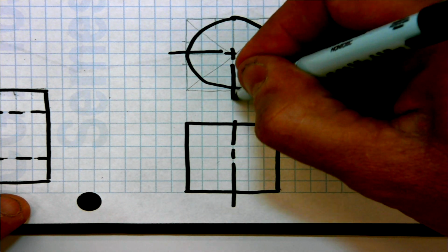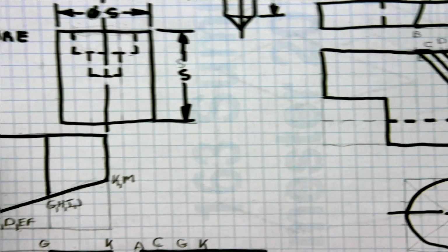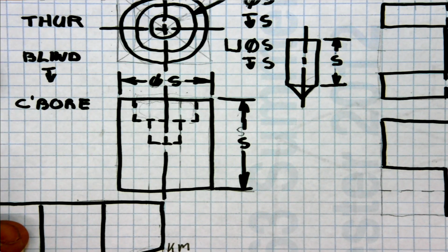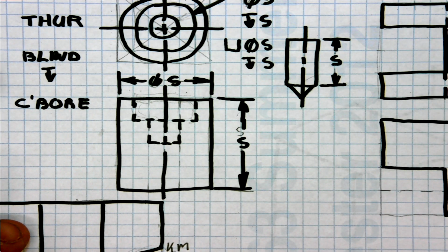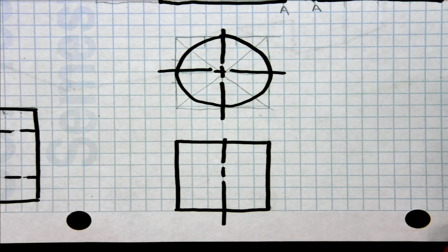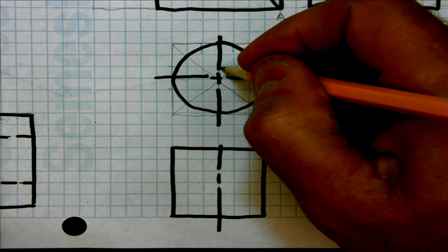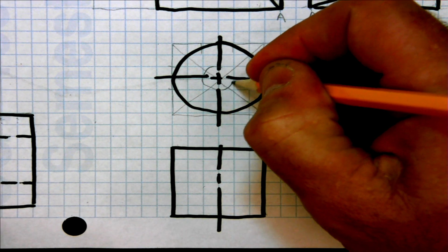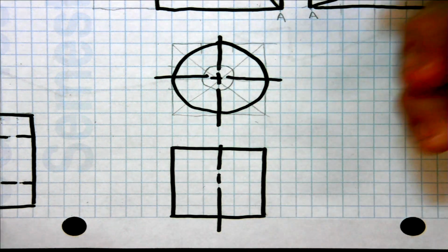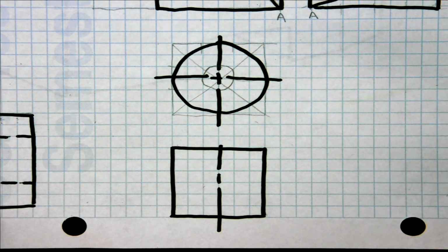Positive cylinder. Again, you would size it. We've done it once over here, there and there. We don't have to do that again over here. All I'm going to be worried about this time is the countersunk hole. Now, like the counterbore hole, the countersunk hole has an initial hole right in here. That hole goes all the way through. It is just a value. If it doesn't, you have to put a depth value.